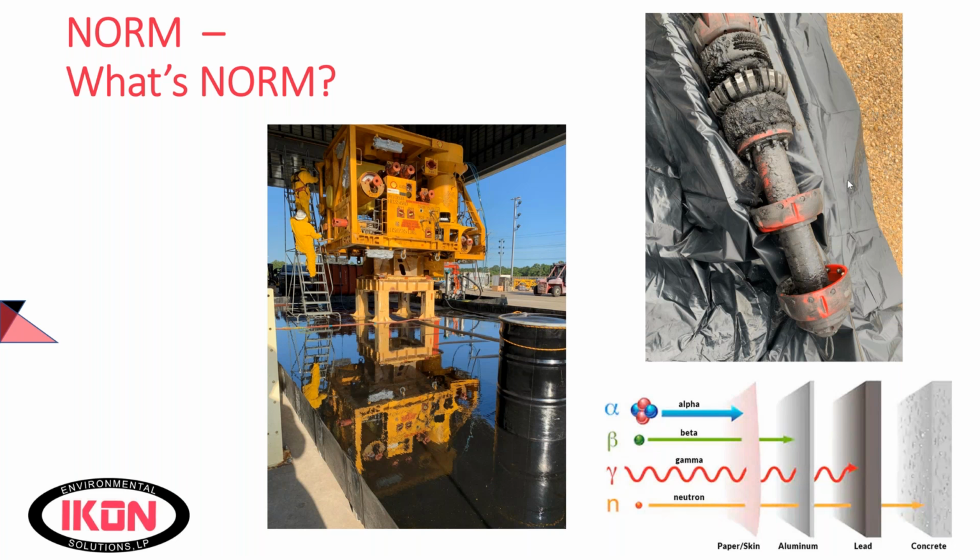Okay. Right, and we've seen some issues a little step further on that. Somebody will measure the front end of a feed line and say they get 200 counts off some internal component there, then they assume that the rest of their plant's going to be less than that, when actually it's kind of the opposite. That's your feedstock, and as you start concentrating the propane, you're also concentrating the radon with that. So you may have components further into your process line that could be tens of thousands of counts when you walk up to them and measure them.